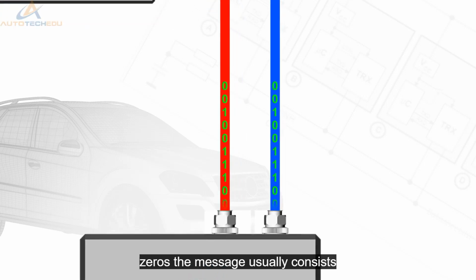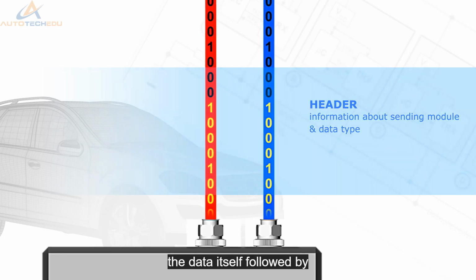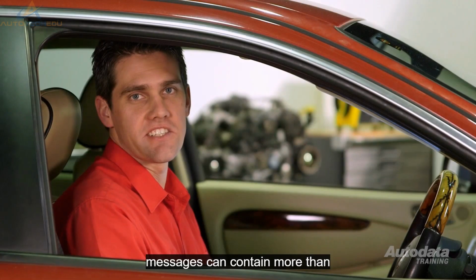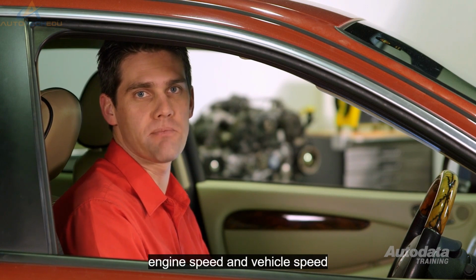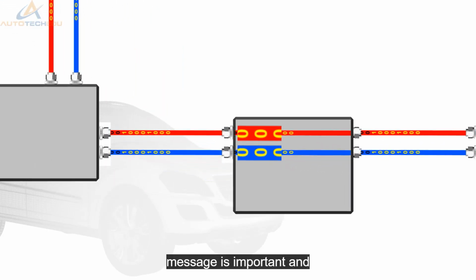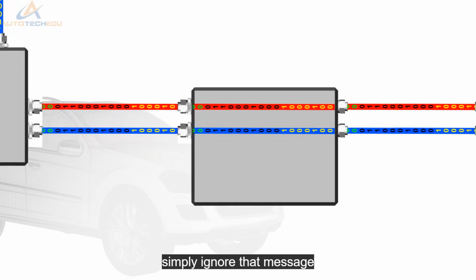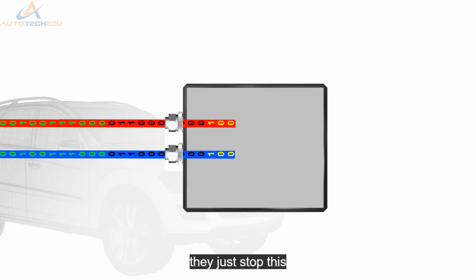The message usually consists of a header, which contains information about the sending module and the data. Next comes the data itself, followed by the checksum, which confirms the message is valid. Messages can contain more than one piece of information. For example, engine speed and vehicle speed. Control units can decide if the message is important, and if not, the control units will just simply ignore that message. When the messages get to the end of the bus, they just stop.